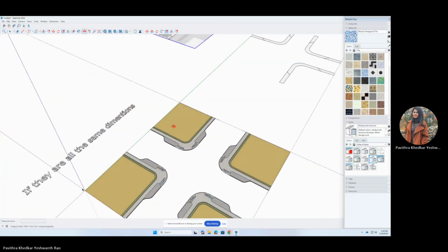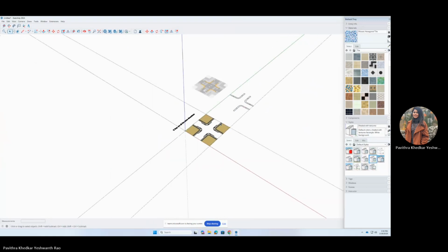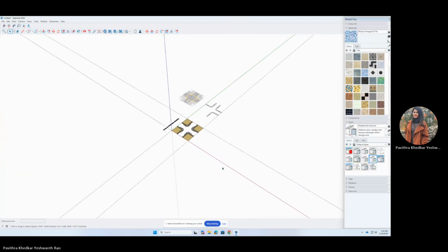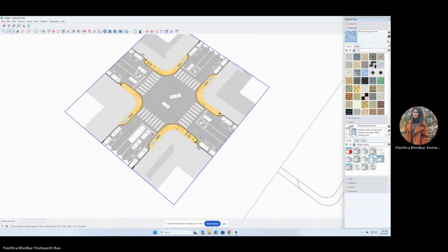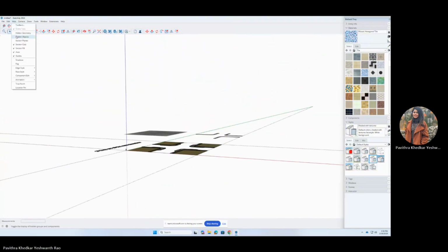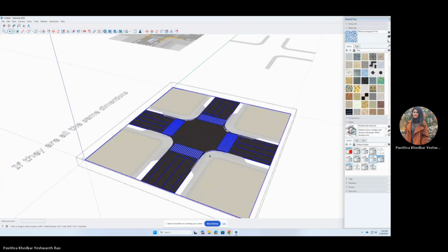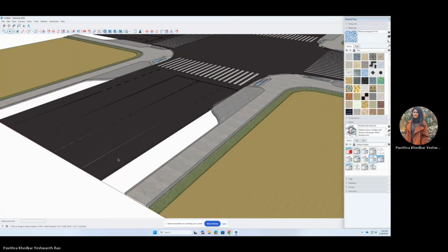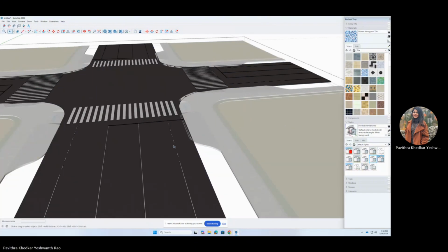Unhiding reference geometry. Unhide all geometry that is not required when you are trying to edit something in isolation. So to make them all appear back again, you do unhide all geometry. For that, you need to go to Edit, Unhide All, to reveal the hidden references.